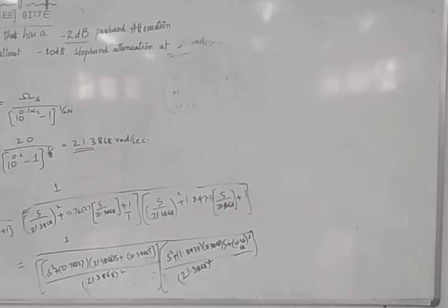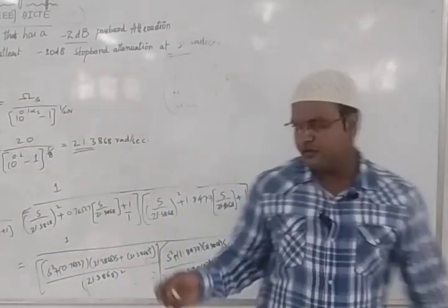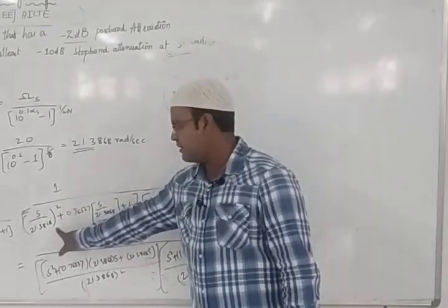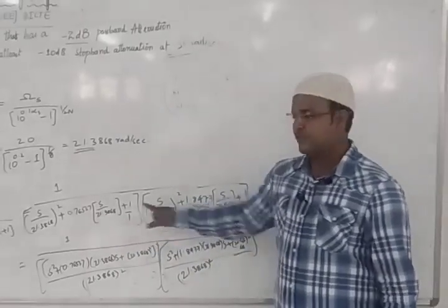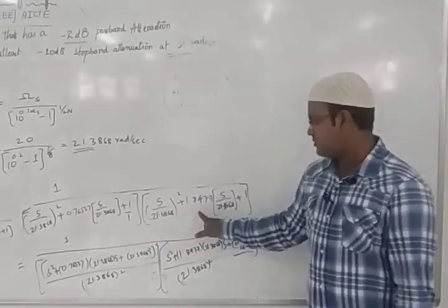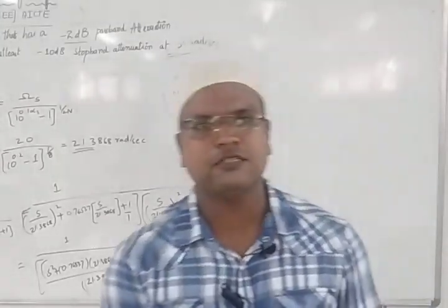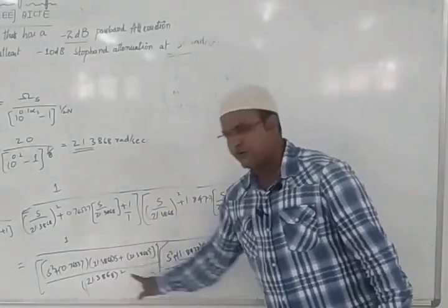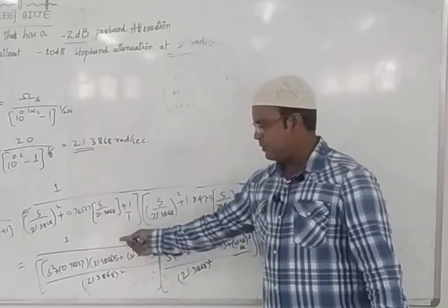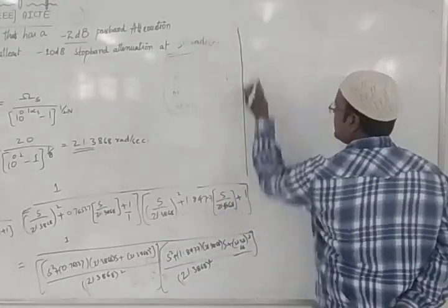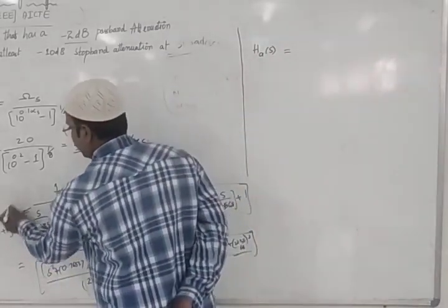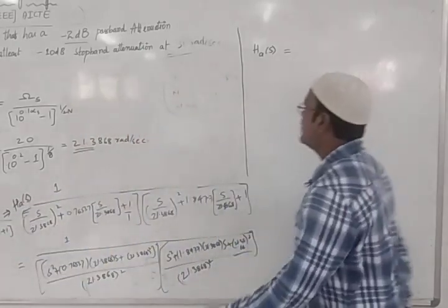So what do we have, students? We had this factor, and we substituted it in the formula. Wherever S is there in H of S, we substituted the critical frequency. So 21.38 is here, here 1 is there, here S square is there, we changed that, and this also. We changed all the factors. Next, we need to find the value. How do we find it? We took the LCM for this factor and this factor, and we got this. In division by division, it will come into the numerator. So we get HA of S. This is your HA of S, the whole transfer function. This is what we want to find. So HA of S is equal to